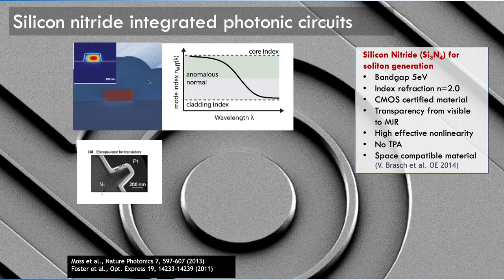The first one is the silicon nitride platform we have been talking about in this conference very extensively. So we'll skip some of the key information. The key information is that it has a really large band gap, so it has a wide transparency window for photonics applications, and it also has high power handling, and it has low two-photon absorption, so we can pump this waveguide really strongly without causing too much damage.